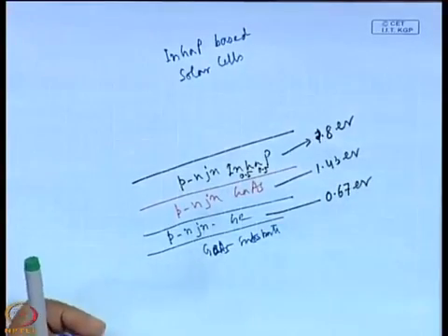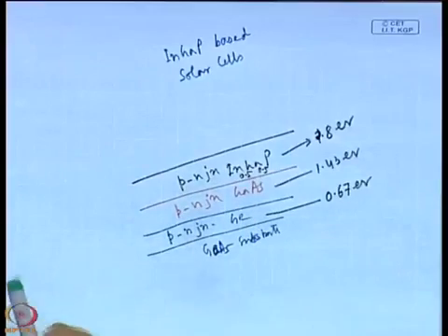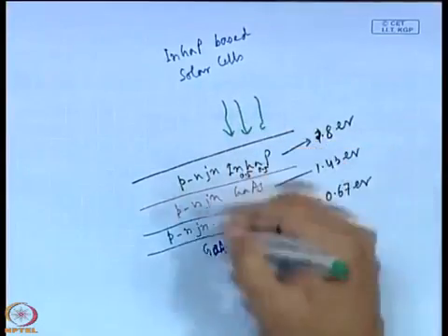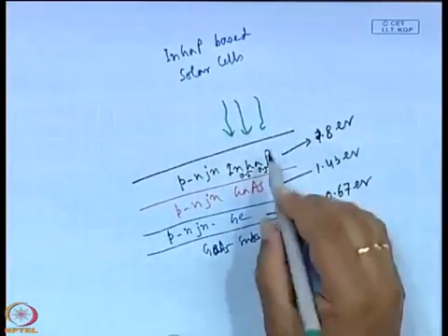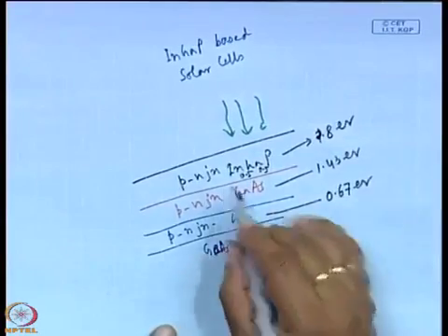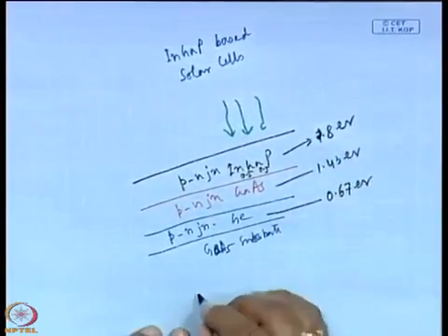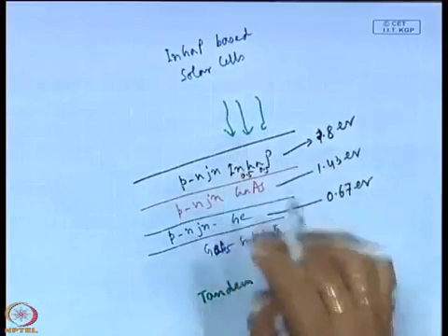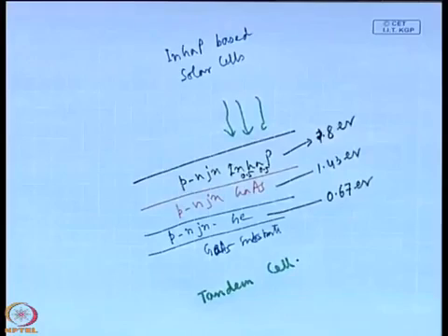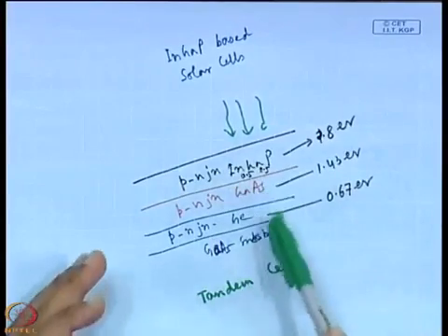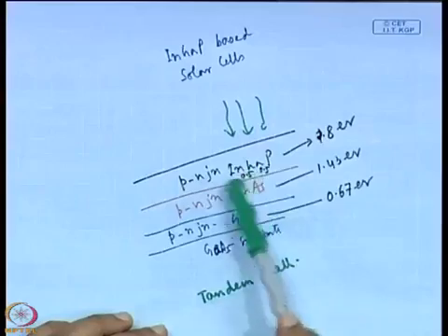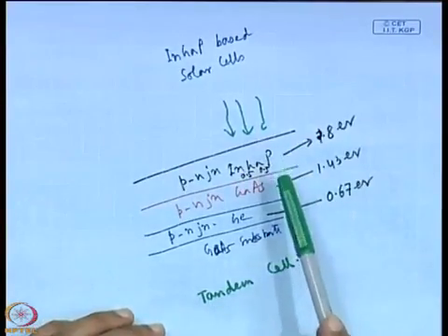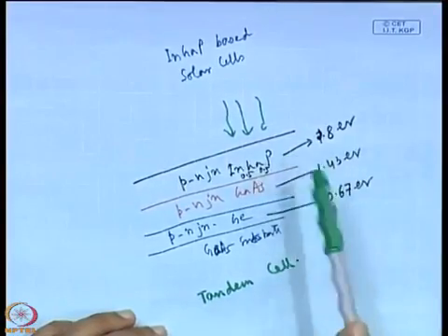And you see that it can harness a substantial amount of the solar radiation and convert it to electricity. So, this type of cell is known as the tandem cell, because there are 3 types of junctions, and I have simplified the structure. Basically the structure must involve a tunneling layer, so that the currents add without any substantial loss, and the output will be better.